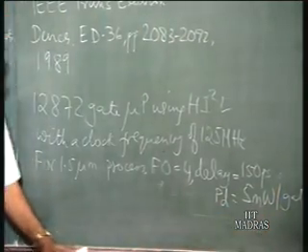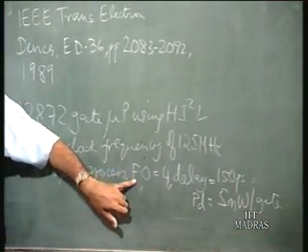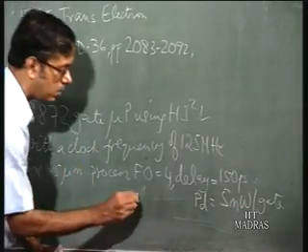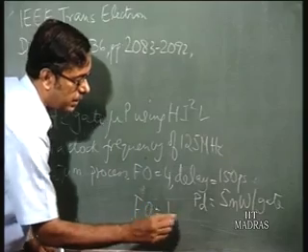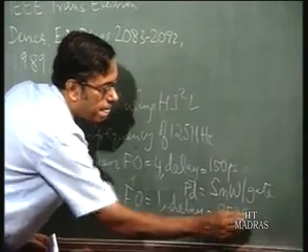Power dissipation was a little on the higher side, but for a fan out of 4, the delay was just 150 picoseconds, and for a fan out of 1, the delay was just 85 picoseconds.